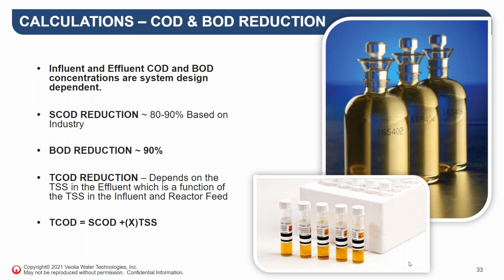So again, it depends on the type of wastewater, but if a typical food and beverage industry type wastewater is what you have, you should be getting soluble COD reductions much greater than 80% and BOD reductions above 90%. Okay.